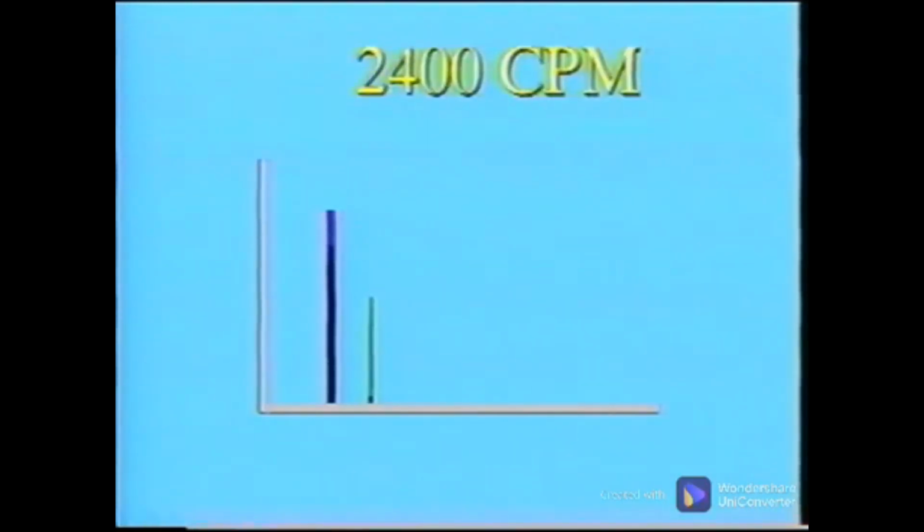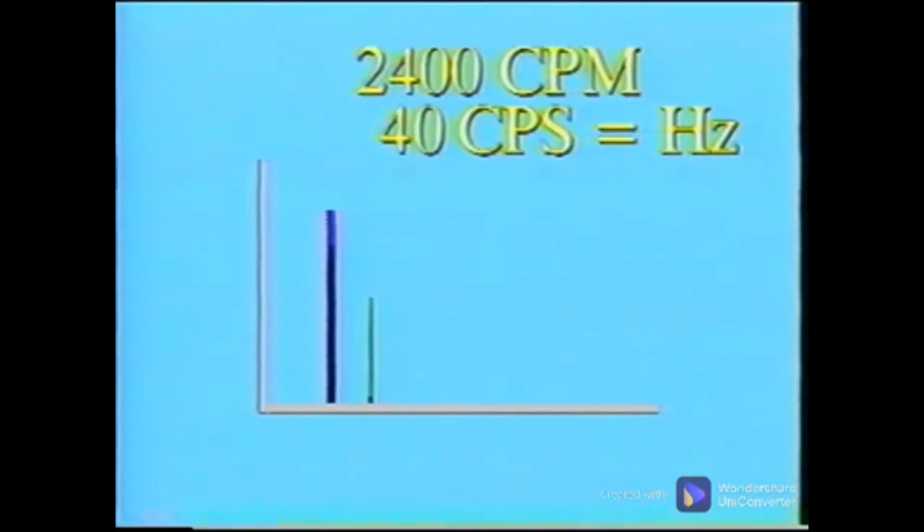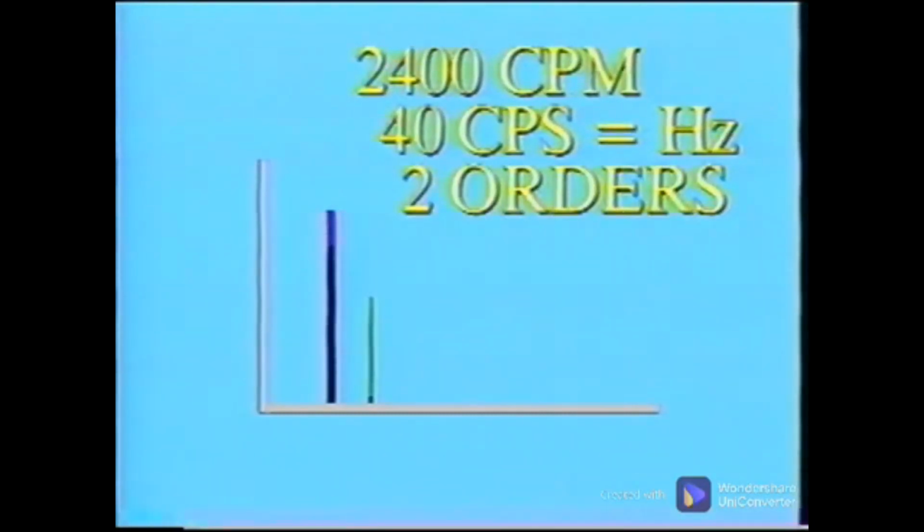The frequency of this new peak can be expressed in each of the 3 frequency units and can be said to show energy that occurs 2,400 times per minute, 40 times per second, or 2 times during each shaft rotation. This 2 times peak is often called a 2-order peak. Here we can see how each of these peaks were generated because of specific mechanical properties.